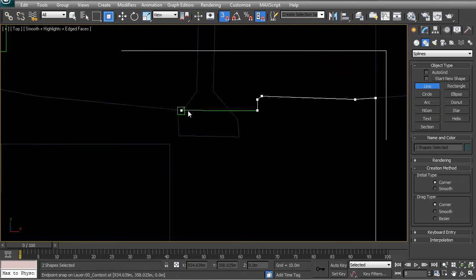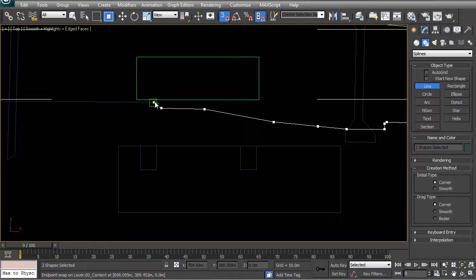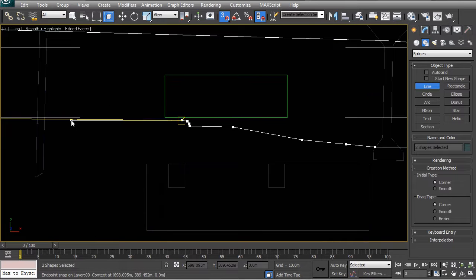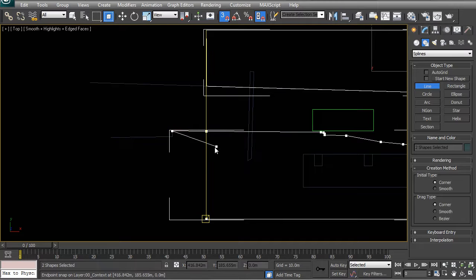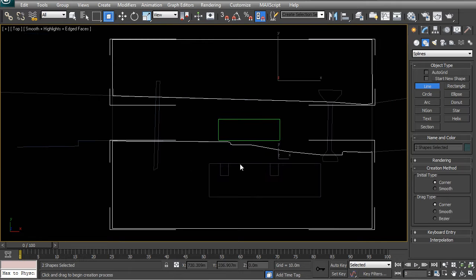And that already brings me to one of the first tips that I'm going to be sharing, is that in order to create a really quick workflow, you want to have as few objects as possible in your entire scene. What that means is that you don't really want to fuss with having hundreds or even more separate objects that you have to individually copy modifiers to and instance them all amongst each other.